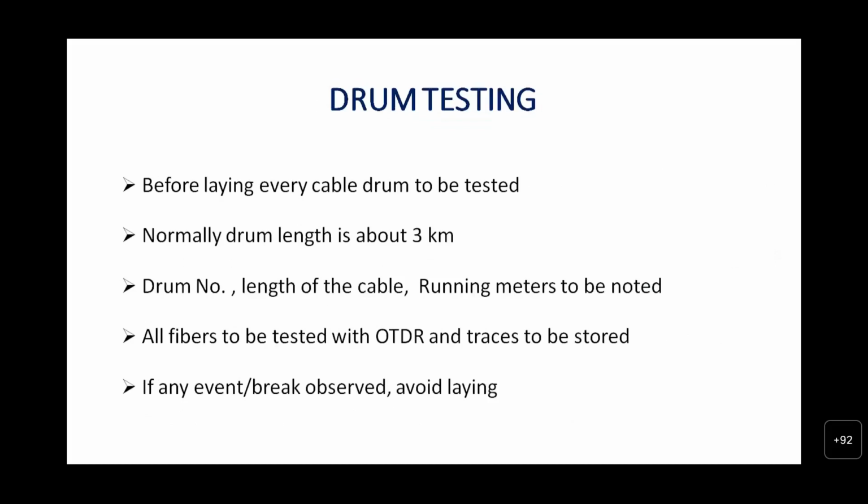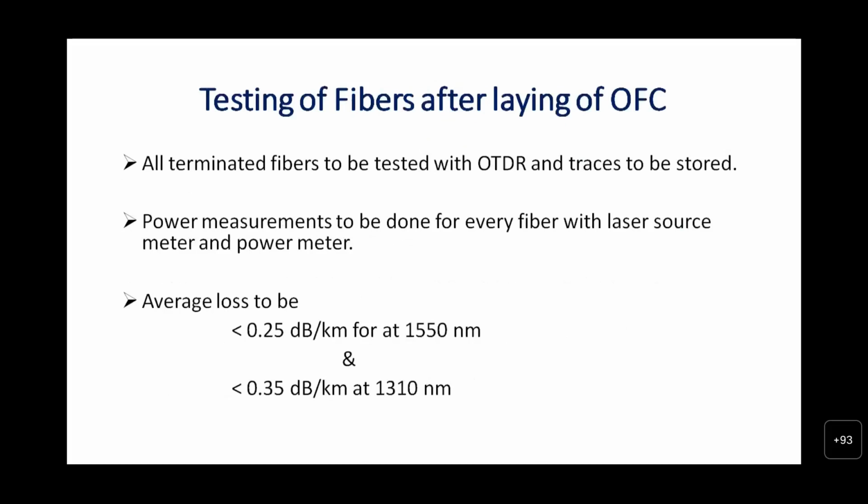As you know, drum number, length of the cable, running meters to be noted. All fibers to be tested with OTDR and traces to be stored. If any event or break is observed, avoid laying and/or reject the cable.